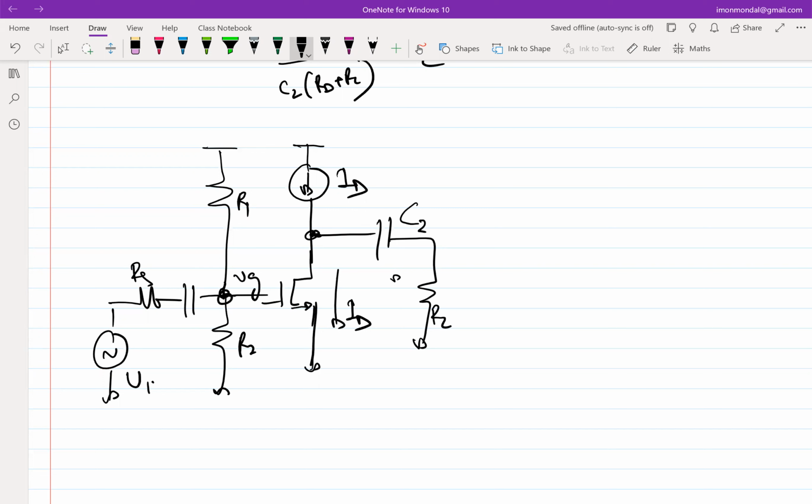How do you know that there will be some current division for T2? Okay. Will there be a current division under quiescent condition? No, because the capacitor is open. It's a DC. No current can go in here, right? So there will not be any current division.